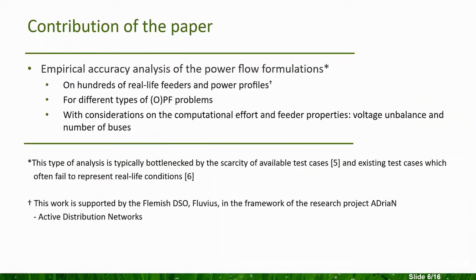The contribution of this paper is the empirical accuracy analysis of the described formulations. This type of analysis is typically bottlenecked by the lack of available test cases, and sometimes the existing test cases fail to represent real-life conditions. What we do is we test the formulations on hundreds of real-life power profiles made available by the Flemish DSO Fluvius for different OPF problems, and with an eye on how the voltage imbalance and number of buses of the feeders influence the results.